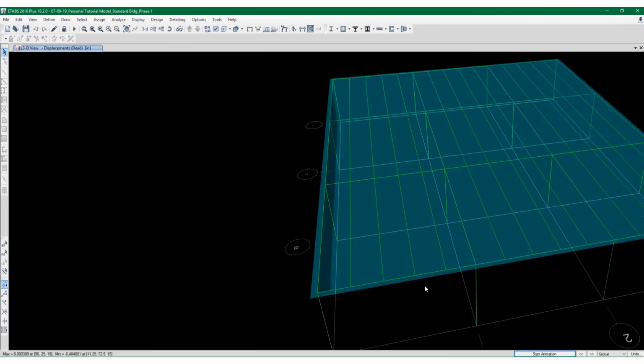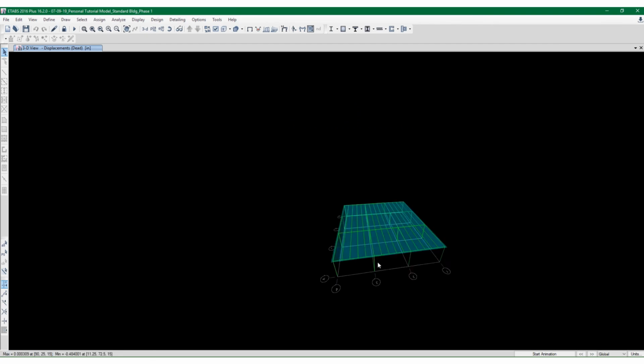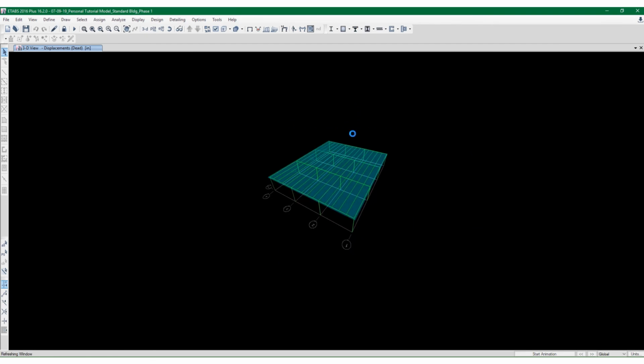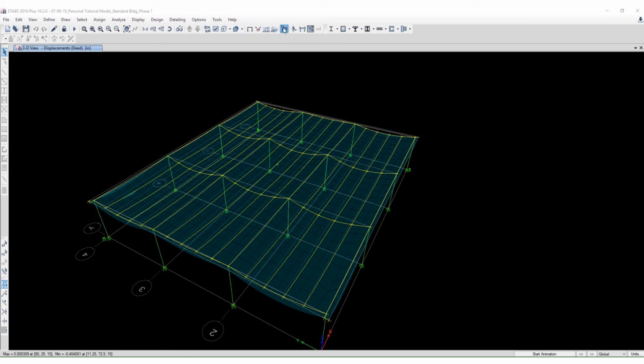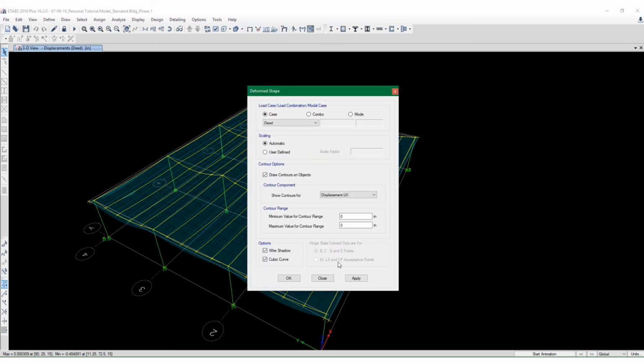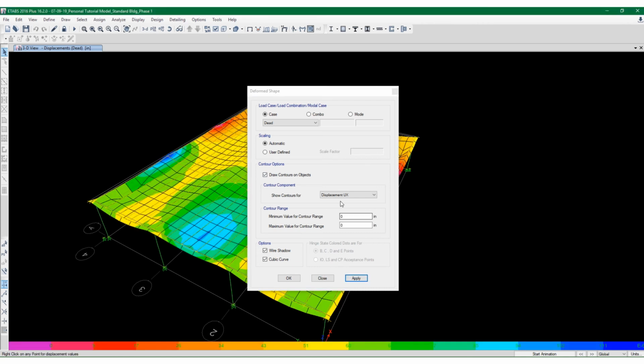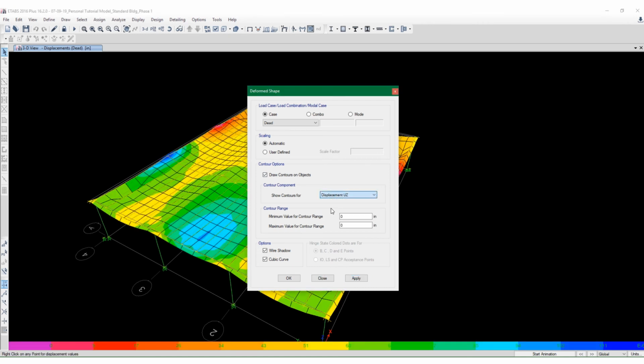Okay, so you know, we could turn on our contours just as well. You can see that there are variations of the deflection along that edge. So that to me is obviously indicating that it's picked up on the beam elements and it's connected, and we are getting a stiffness distribution in the vertical direction that we would expect.